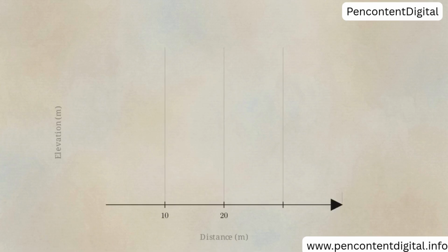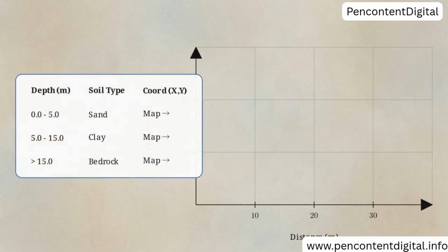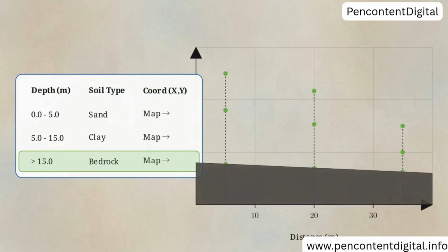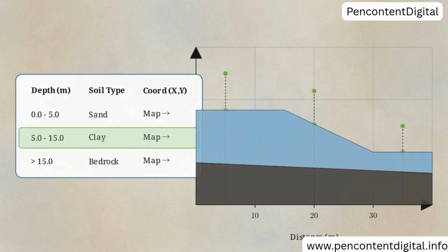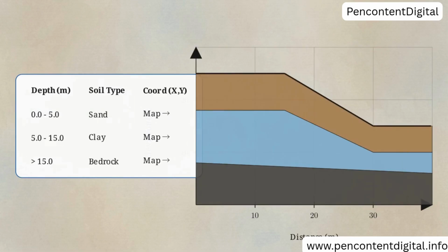We start with a stark 2D coordinate grid. This is the blank spatial canvas where the engineering model is constructed. Engineers first import raw soil investigation reports and borehole data directly into the software interface. Using this raw data, the software maps out the soil stratigraphy, snapping distinct color-coded layers into the grid to form a precise cross-section of the multi-layered slope.